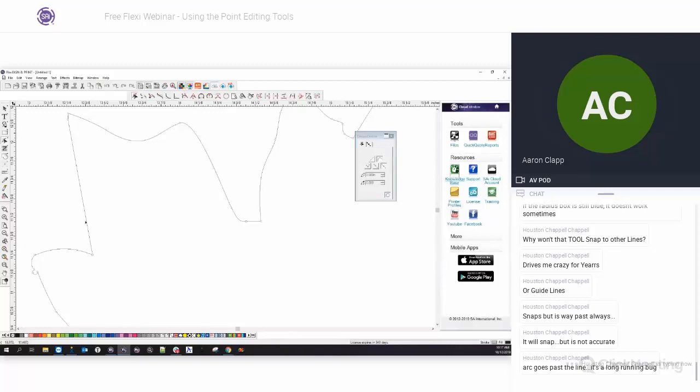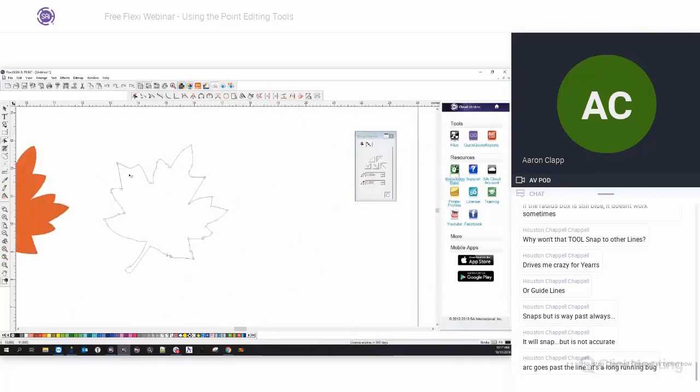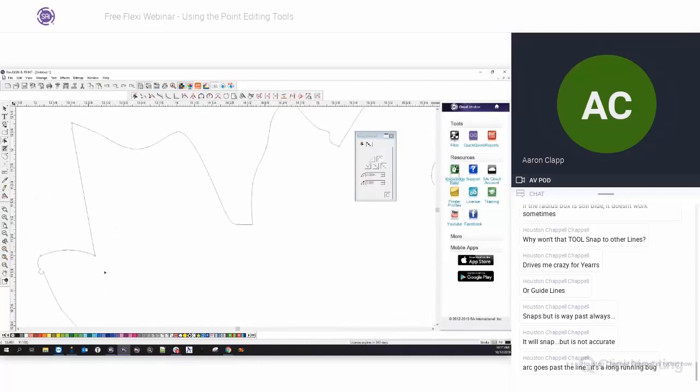It simply just reduced the amount of information, which when you're trying to process a file or add a contour cut to it, or even just zoom in and zoom out, having fewer points available in the file for it to mess up is really nice. So that's just a nice thing to do. I would always recommend it right after a vectorize. Just run a quick reduce points, set the tolerance super low so it doesn't change the graphic, and that'll make it so that you don't have hundreds of thousands of points in a vectorized file, which can happen sometimes.